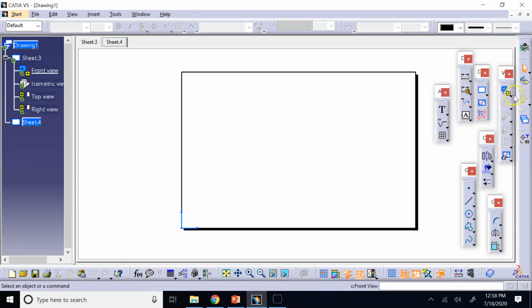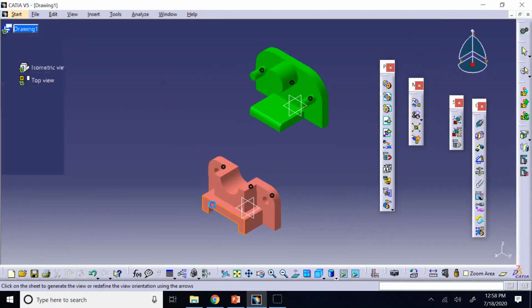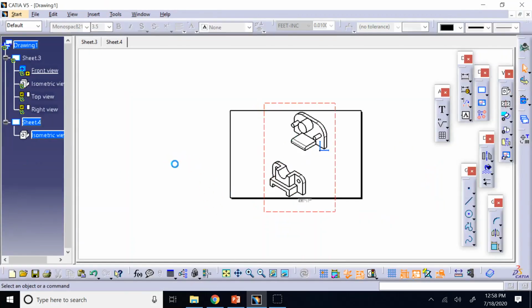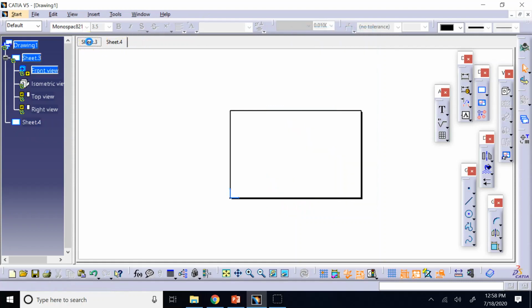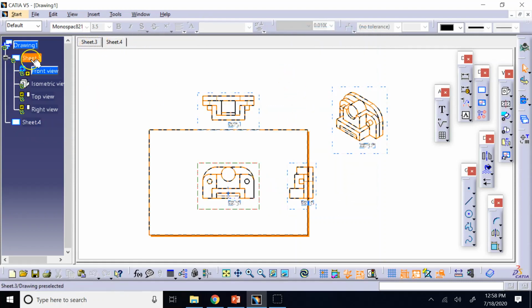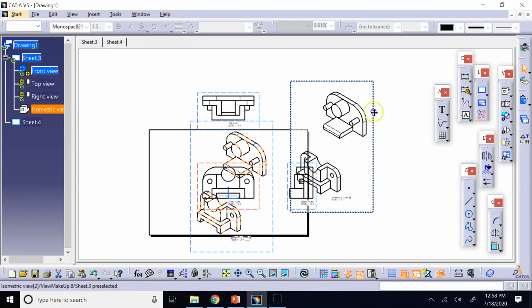So I go here and I want only an assembly view. And then I choose a front plane. And now look. Yes? So this is how you would get an assembly exploded. And if you want, you can cut this and bring it back here. Yes? And you can get rid of this if you don't like it.